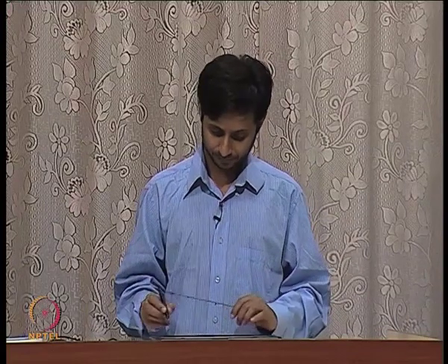Okay. If I increase R, if I double the value of R, the cutoff frequency is going to go down by 2. So, lesser frequencies will pass through. Okay. So, the total noise I will see at the output is going to be lesser. All right. So, this is basically the idea.